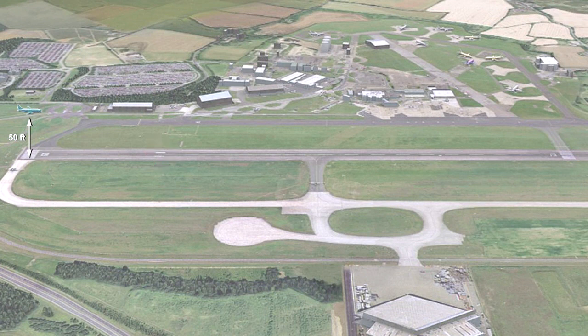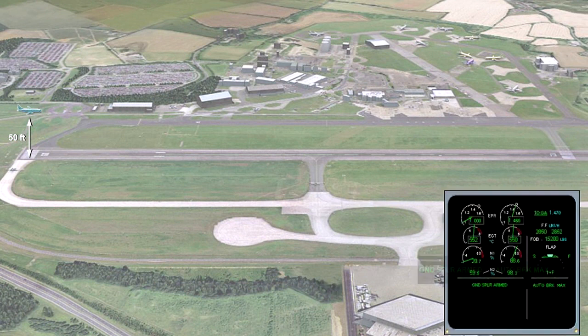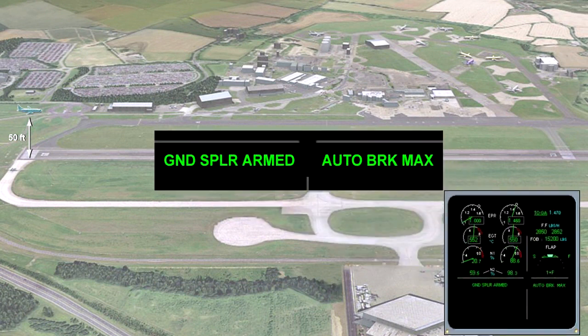Land on the centre line with minimal lateral drift and without excess speed. Arm auto spoilers and auto brakes as appropriate, which assure prompt stopping effort after touchdown. For aeroplanes fitted with automatic anti-skid brakes, the brakes will be applied above the dynamic hydroplaning speed, but for aeroplanes without this system, only apply the brakes below the dynamic hydroplaning speed.